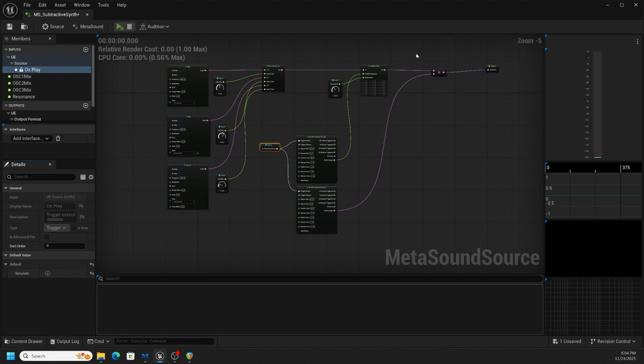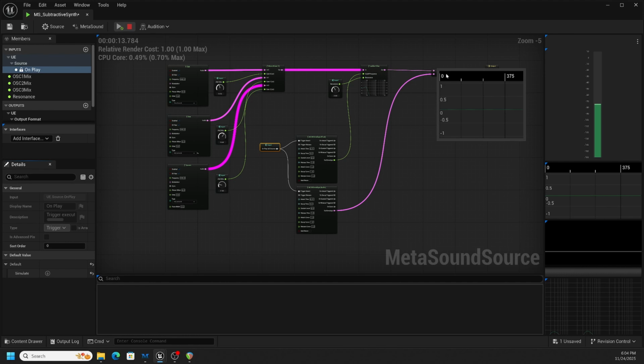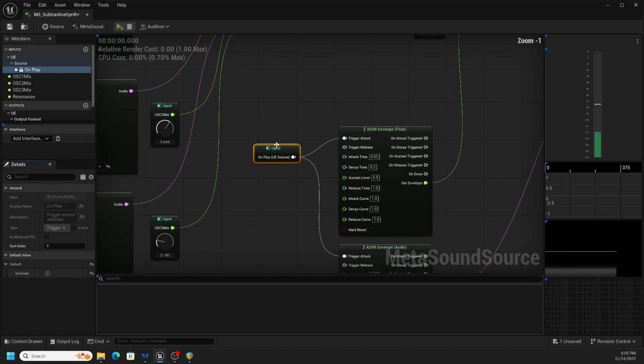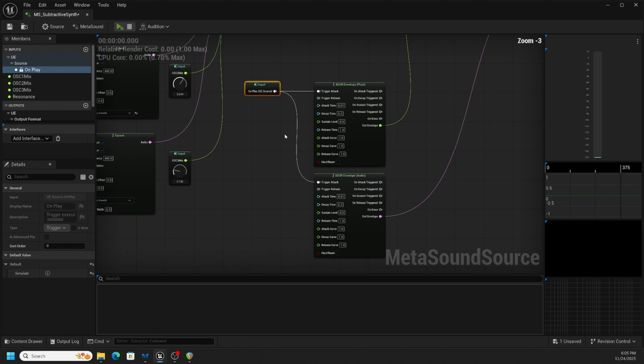Okay. After I hooked up this VCA, we really couldn't hear any of the signal coming through, right? If I hit play, all this audio is coming through, but it's getting blocked by, well, both the filter and the VCA. So we need the envelopes to be working in order to hear any of the signal. So it's going to be much more efficient to go ahead and test our envelopes to see if they're working before hooking up all of the MIDI stuff. So I'm using the input trigger temporarily to trigger my envelopes to test this signal.